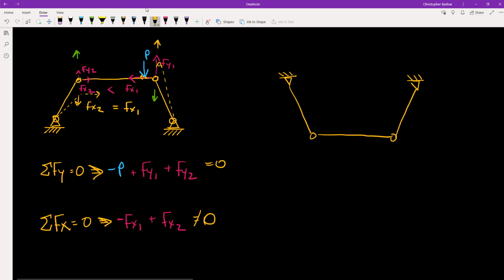So that actually sounds like exactly what we need. We needed those horizontal components to balance out. And if these joints realign this way, eventually that's exactly what would happen. They would balance out. But there's one small problem with that. In order for this joint to move up on the right here, this heavy weight, this applied load, would also need to accelerate up against gravity. And how often do you see weights move upward on their own? Well, hopefully never, because that's not how gravity works.